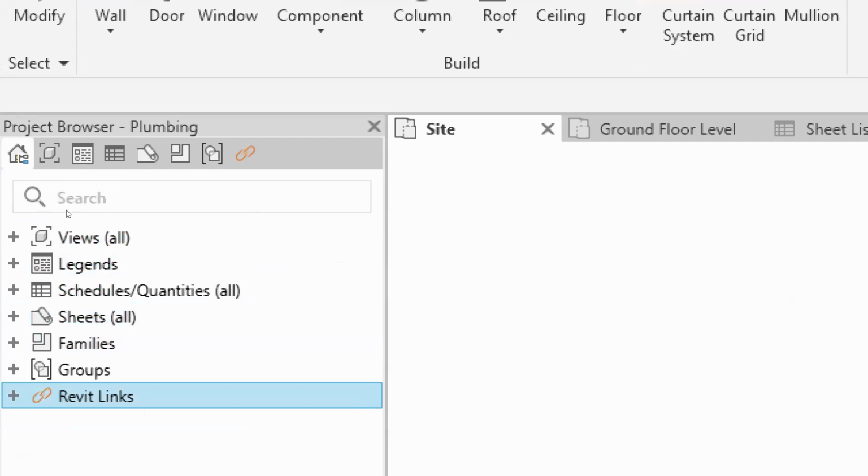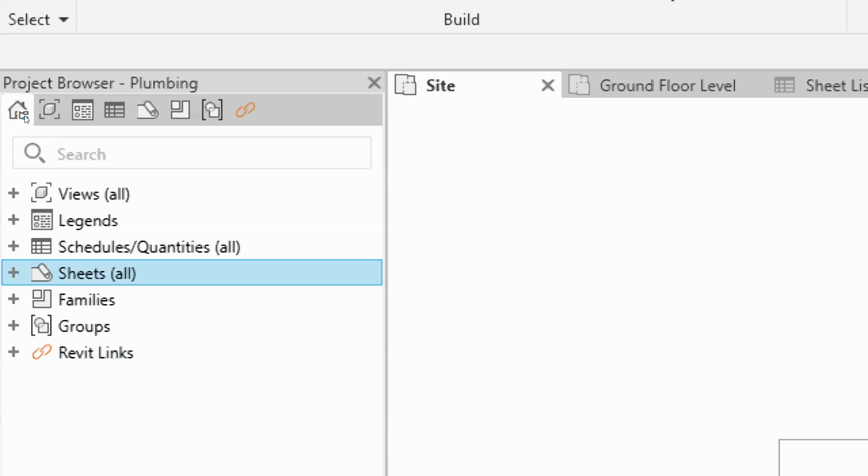Any sheet that we are going to compose, which will fall here, is going to be a combination of views, legends, and schedules. The way you arrange your sheet in terms of views, legends, and schedules will give you an opportunity to tell a story to whomever you are going to present the sheets to. It is not just that you create a sheet and then put anything there. Most of the time, people just start with ground floor plan, first floor plan, second floor plan, section 1.